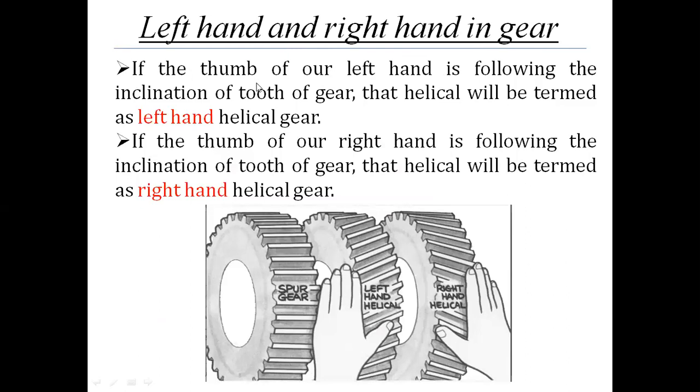gears. If the thumb of our left hand is following the inclination of tooth of gear, that helical will be termed as left hand helical gear. And if the thumb of our right hand is following the inclination of tooth of gear, the helical will be termed as a right hand helical gear.